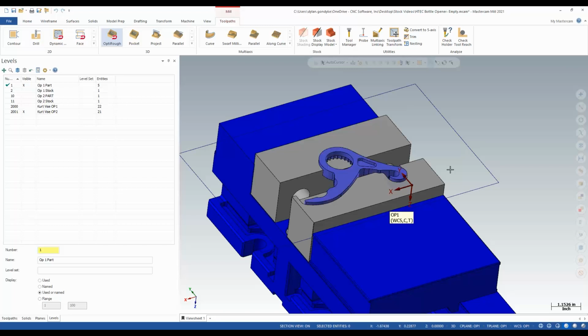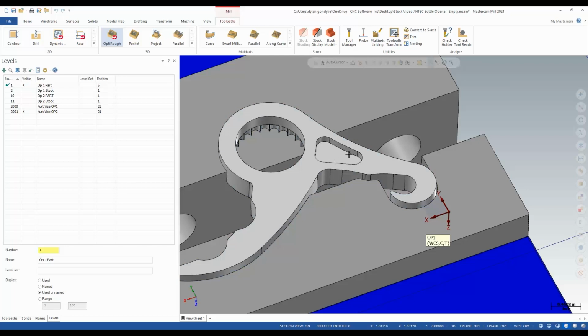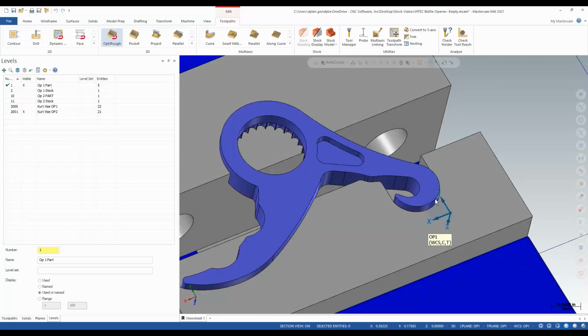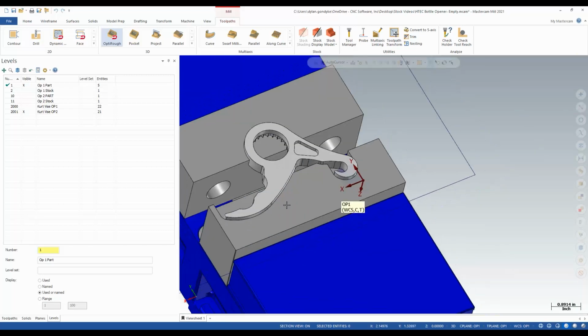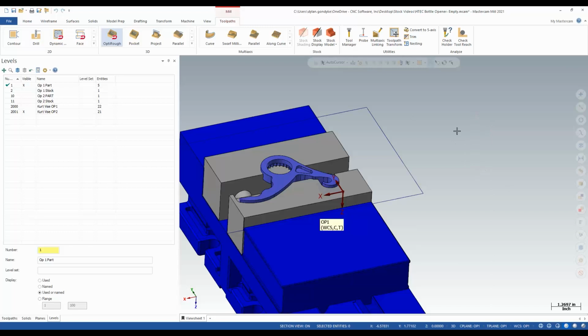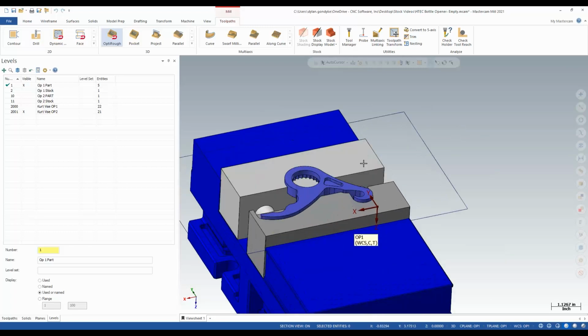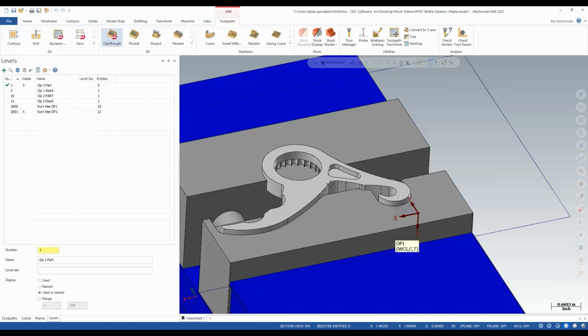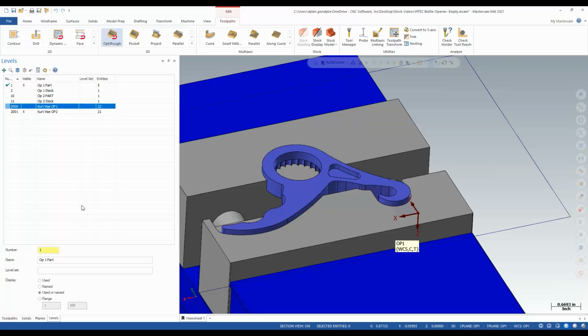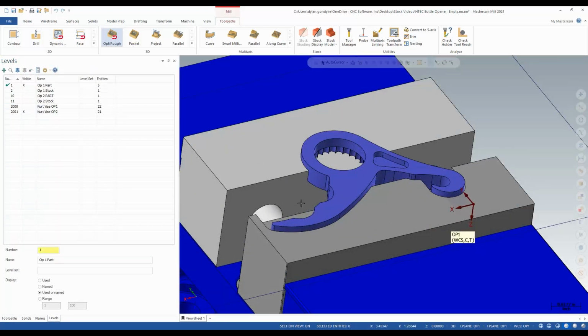So let's say we change this bottle opener. Maybe we make the pocket a little bigger. We change the hook shape so the caps come off the bottles easier. If we had physically copied our bottle opener and drawn the twin vise setup here, we would have had to make that change in two locations. In other words, we no longer have one master set of geometry driving all of these toolpaths. We have two, and we need to selectively remember what paths affect what and what geometry is being used, and it gets to be a little overwhelming.